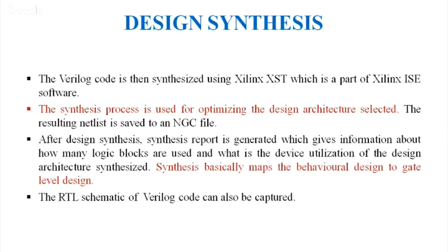The third step is design synthesis. Design synthesis is basically used when we do implementation of our code. The synthesis process is used for optimizing the selected design architecture. It gives the netlist, which is saved in the NGC file format. In this step, a synthesis report is generated, which gives information about how many logic blocks we are using.